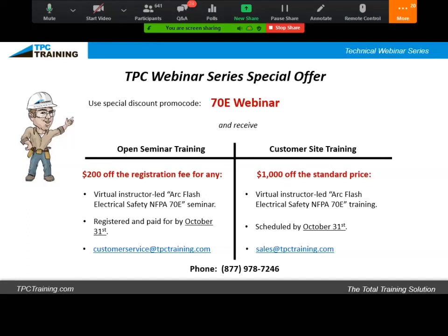And there's 8 of those steps. Those steps now have to be part of your electrical safety program. They have to be spelled out. And you should monitor those steps when a worker is de-energizing a piece of equipment, and he has to go through all 8 steps and their verification process. It has to be part of your electrical safety program, because a lot of injuries are caused because we didn't follow the right procedure. And so that procedure now has to be part of your safety program.